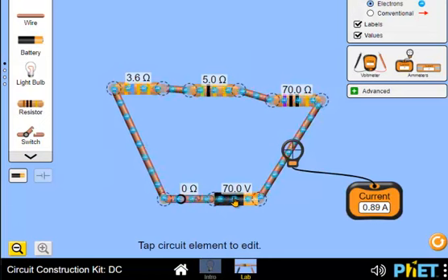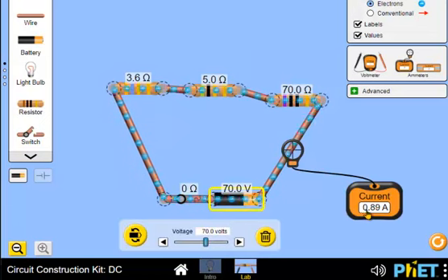So what I'm going to do is increase the battery voltage here until I get a nice 1 amp, and then I'm going to use Ohm's law. Okay, so I'm going to get up to here, they're really close. There we go, 1 amp. So here I have now 78.2 volts divided by 1 amp. Ohm's law gives 78.2 ohms, but because I've shifted the decimal point, it's 782 ohms, which is, within rounding, the same as the 786 that I had earlier. By the way, if I push this up a little bit, notice that there's my 78.6, right? Shift the decimal point, and my current didn't change. That's because of sig figs. Okay, that's a series circuit.